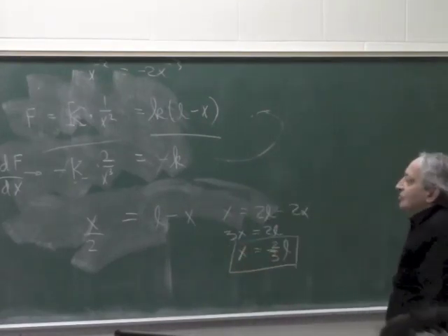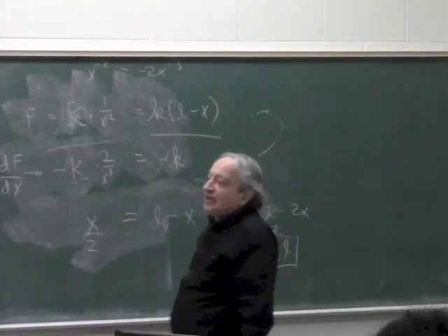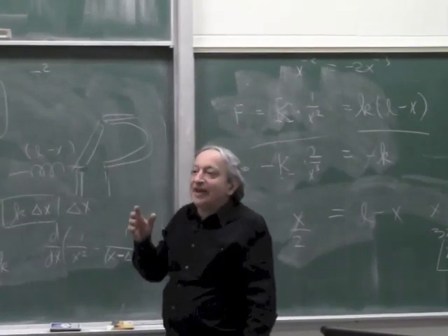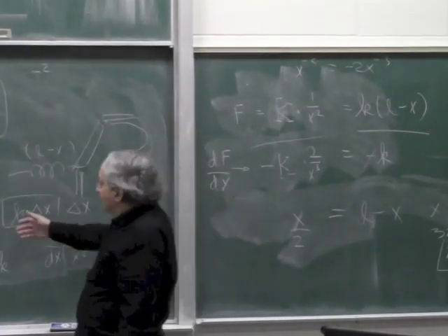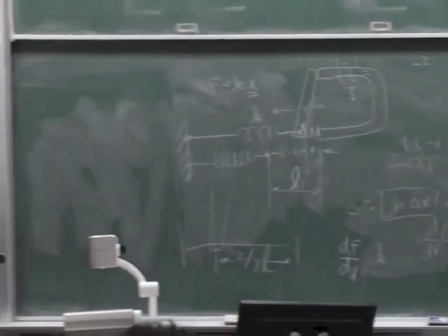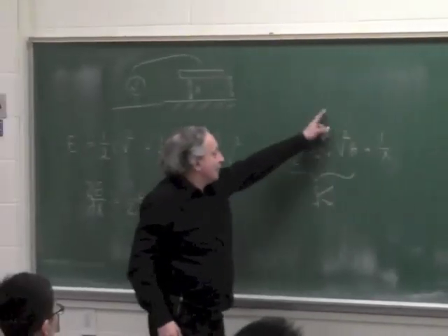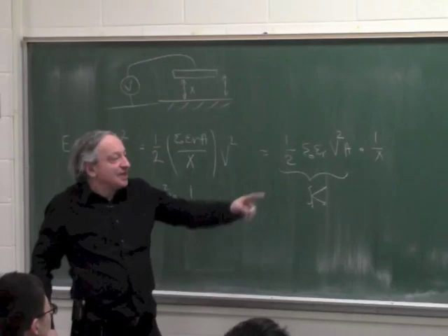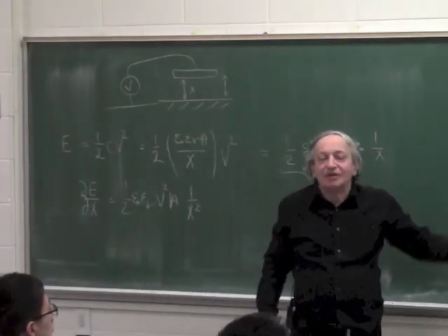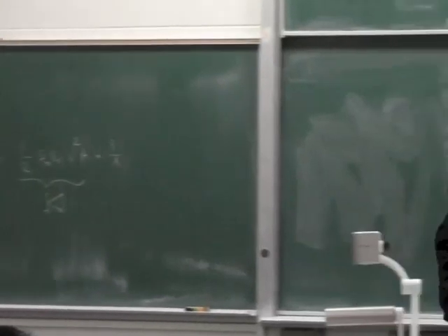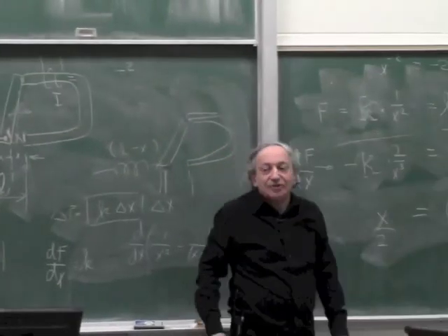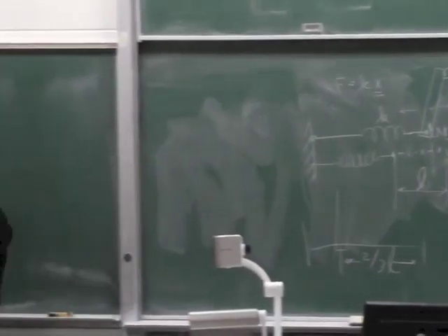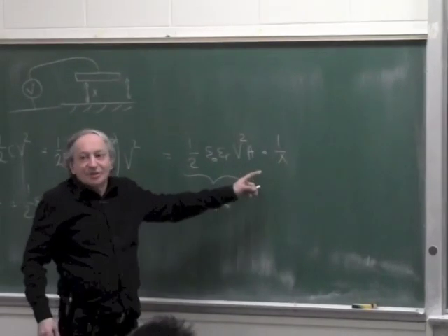Good. Okay. So bottom line, when I have a moving iron actuator, and if you think for 1 second, this will be true for any 1/x² actuator, because if I did the same analysis for this, I'll get the same results, because this part is a constant, so the rest of the equation is the same as that part. So in this case, the constant is the constant of the moving iron. In this case, the K is the K of moving iron, which was 1/2 I squared mu A and all this. In this case, the constant is the electrostatic actuator constant, but in both cases,